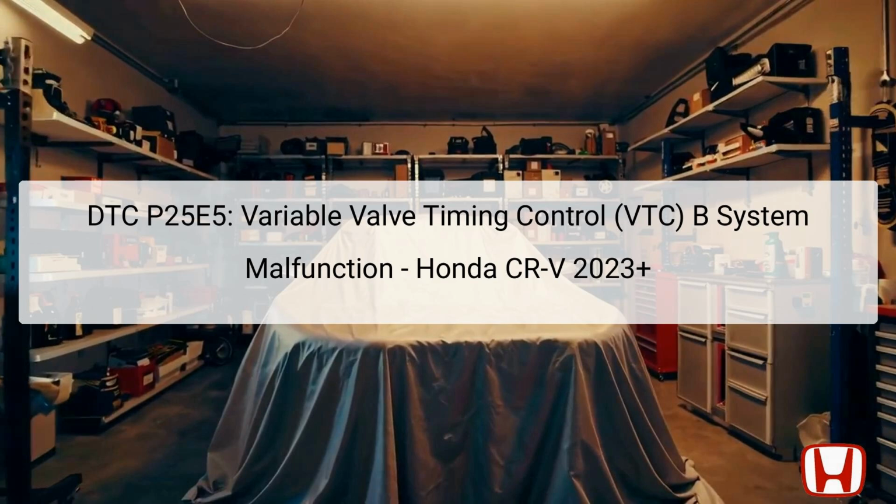The exhaust camshaft plays a crucial role in higher RPM performance, allowing the timing of the exhaust valves to open and close at the optimal moments for engine efficiency. This phase control discrepancy can lead to decreased engine performance, poor fuel economy, and increased emissions. Knowing the components involved and their functions is vital for accurate troubleshooting and repairs. The following slides will guide you through a comprehensive troubleshooting process for DTC P25E5.